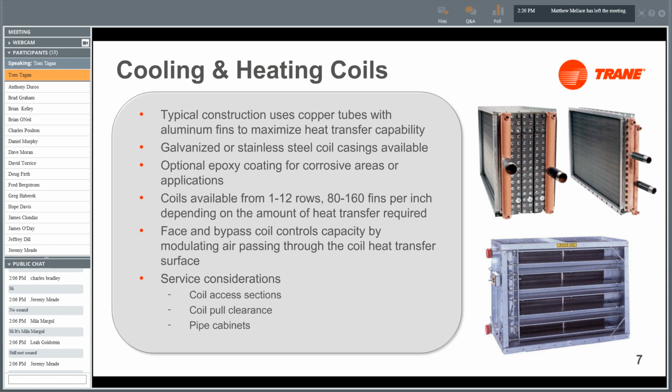Now, when selecting coils for an air handler, there are a few service considerations that you want to keep in mind. Coils need to be periodically cleaned in a unit, so to do that you need to have access sections upstream and downstream. You also want to have room to mount control components, so discharge air sensors, low limit switches, things like that. So if you don't carve out room for your air handler in design, it's going to be a nightmare for your maintenance people to get in there and clean coils or replace control components when things fail